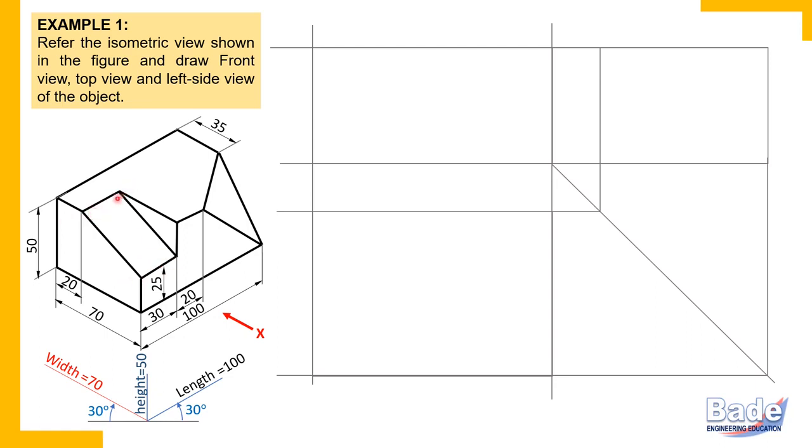Edge parallel to length. Principal edge. Focus on principal edges always. So this edge is parallel to length and length is always perpendicular to PP. So that means this surface is perpendicular to PP, profile plane. And therefore this surface will appear a line. Surface will not appear in the side view, it will appear simply a single line. So this surface is a line in the side view.